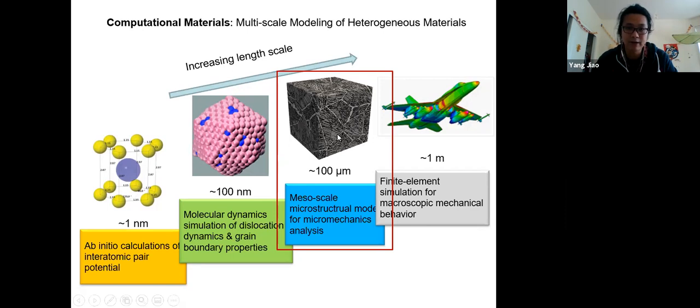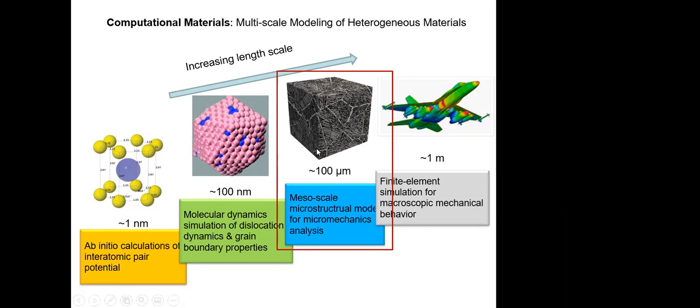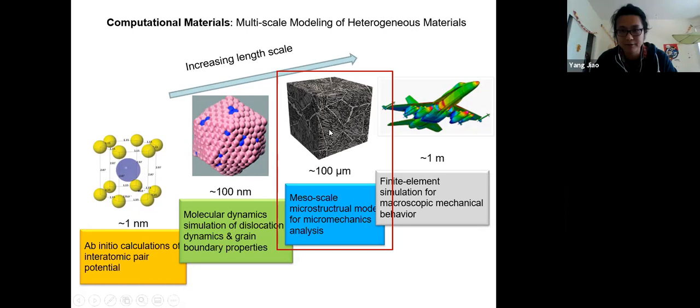What I show here is a simulated small chunk of titanium alloy. The size of this is probably several hundred microns in each direction. And what you can see here is the complex grain microstructure. These polyhedral-like tessellations are the primary alpha grains, and these much finer directional lines are the beta grains, and these are formed during the particular solidification processes related to how the material is manufactured.